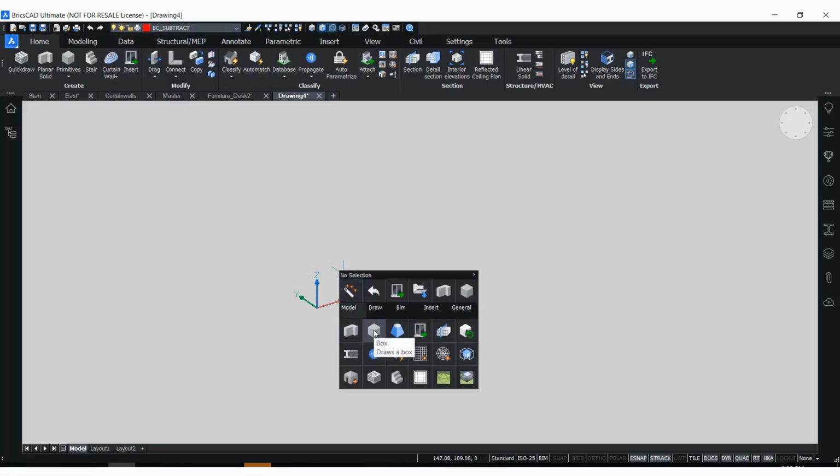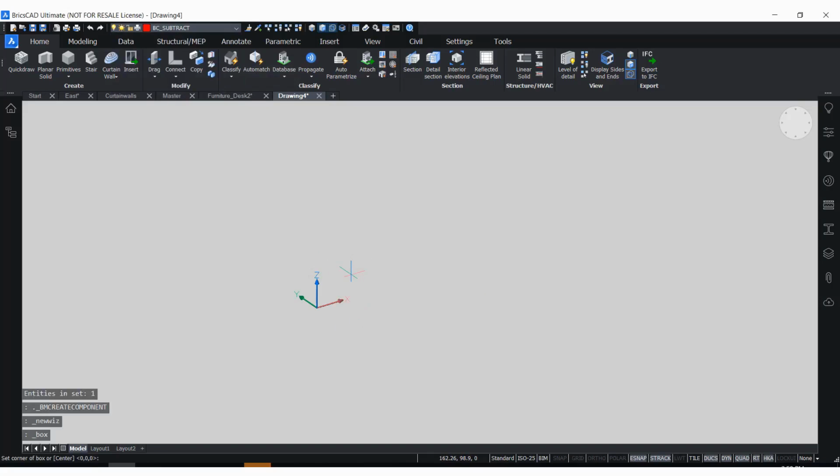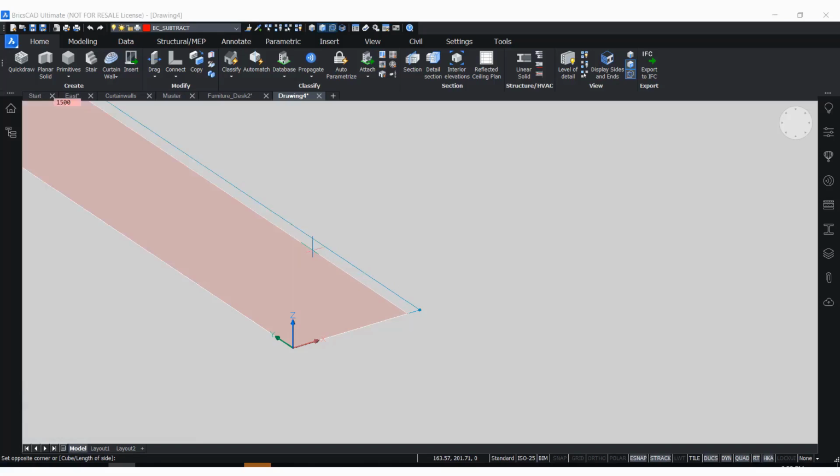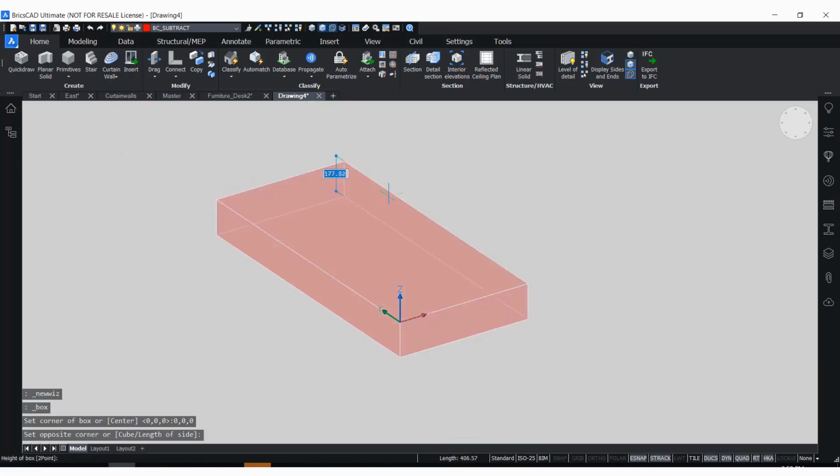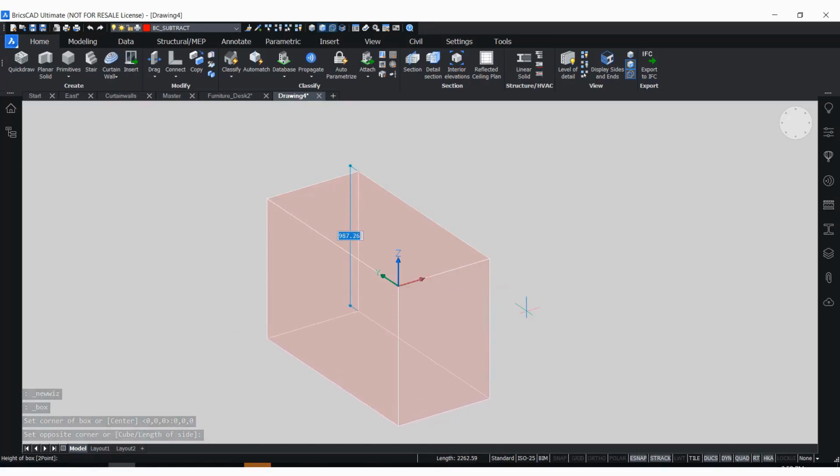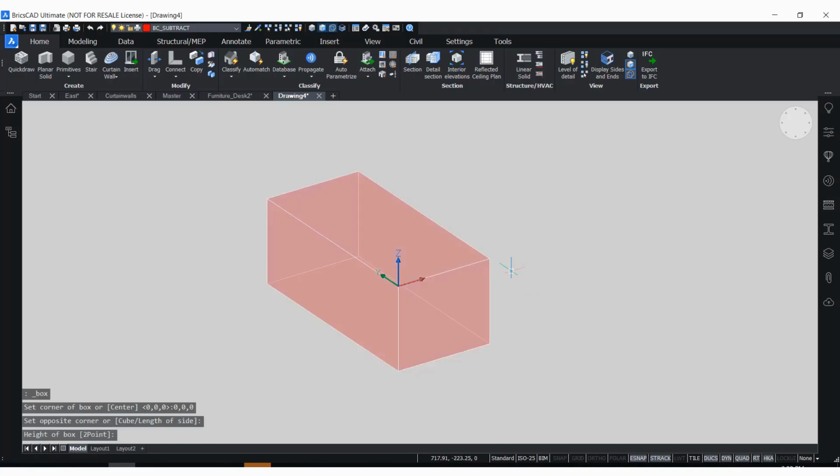Now from my quad, I'm gonna access the tool to create a box. I will go ahead and put starting from the 0.000. And let's just follow what our document has. Let's give it a dimension of 1500 and then 700. And once I click enter, I get to put the depth of it. I'm gonna go downwards and I will put 600. It's not so important, the 600.